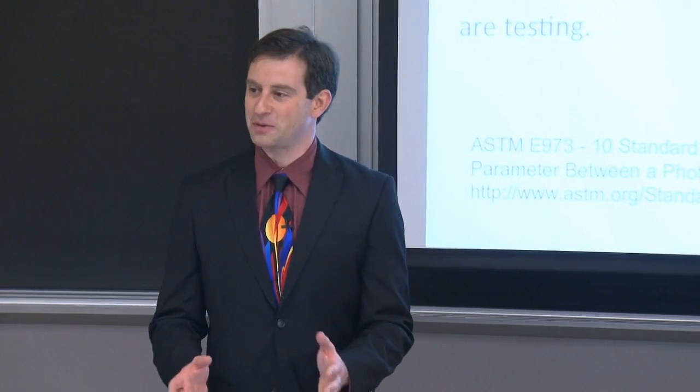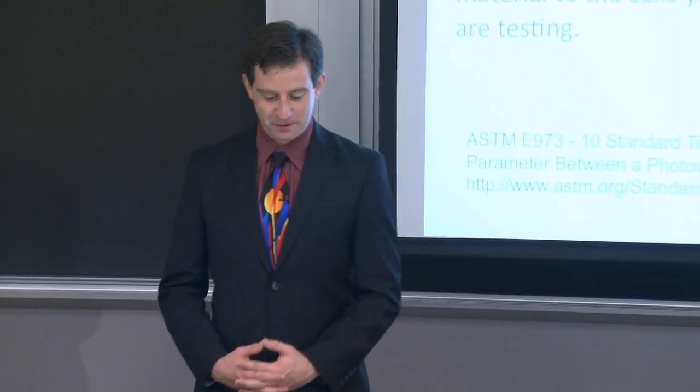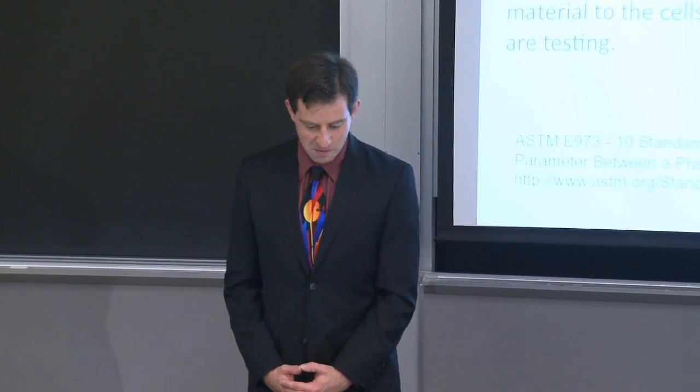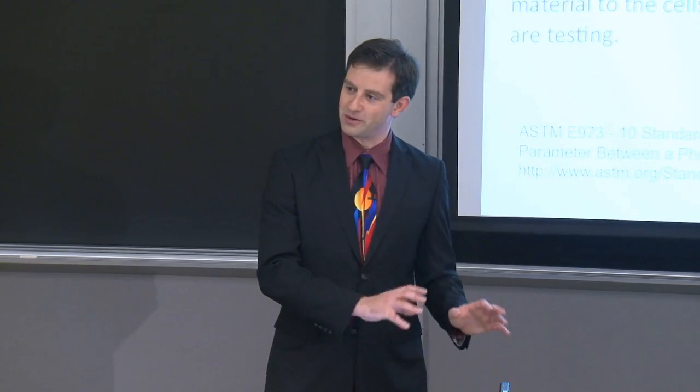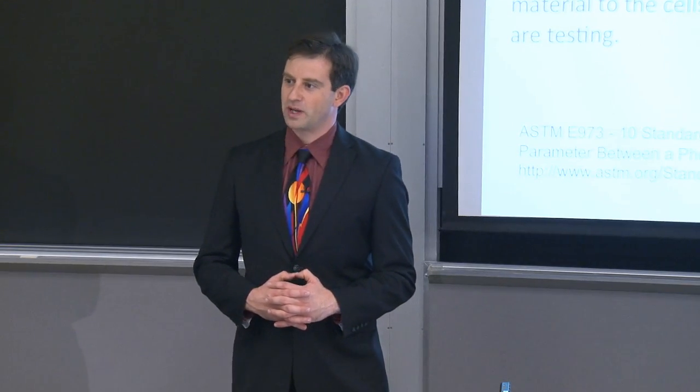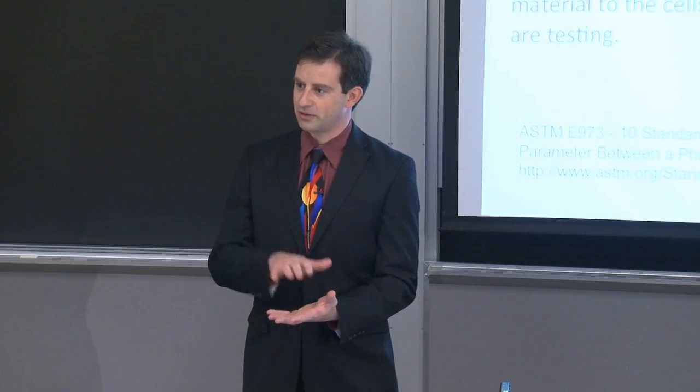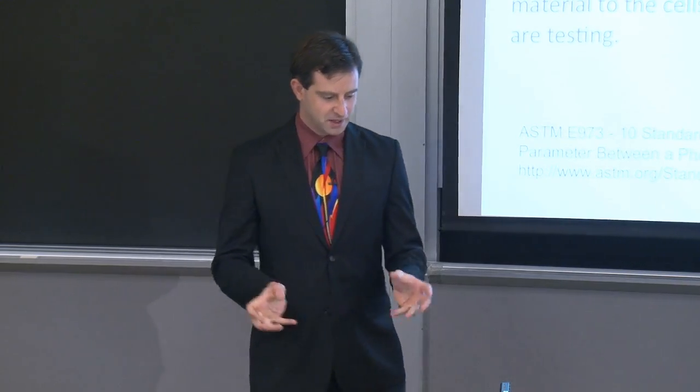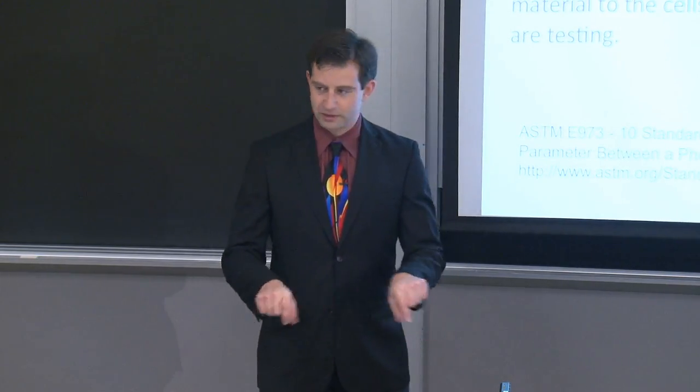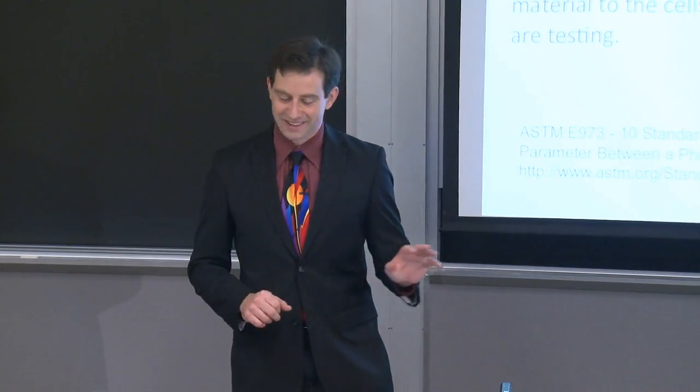If you follow a set of standard protocols that you can receive from the folks at NREL, I believe Keith Emery might be a good point contact first. There are a very specific set of protocols that you should follow if you want to make your own in the lab. In other words, you have to design the contacts a certain way, the encapsulant a certain way, make sure that the materials comprising the remainder are black so that they don't reflect the light back in. Little details that are only gathered by experience.